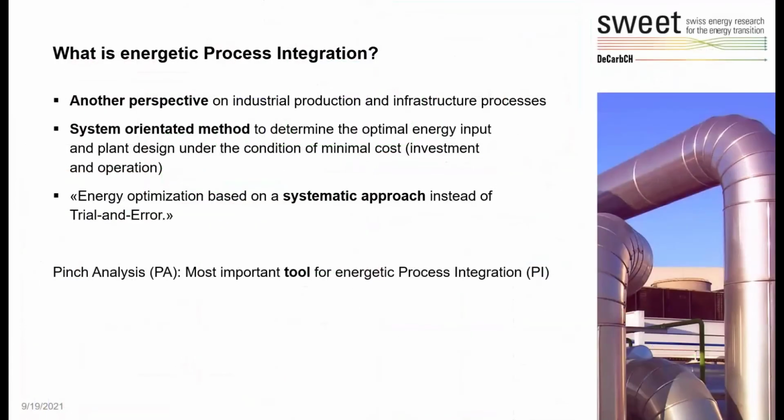So what is energetic process integration? As noted in the first point, it offers another perspective on processes and how they behave energetically. Most important is the second point in that it provides a system-oriented method that allows an engineer to determine the optimal energy use and plant design under the condition of minimal cost. The third point more directly states energetic process integration is energy optimization based on a systematic method and avoids the more common trial and error approach. The most important tool used for energetic process integration is pinch analysis as described on the next slides.